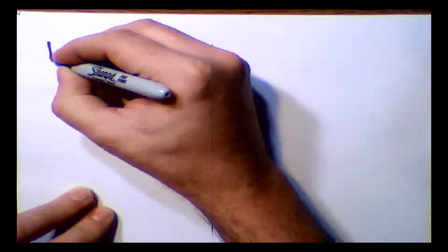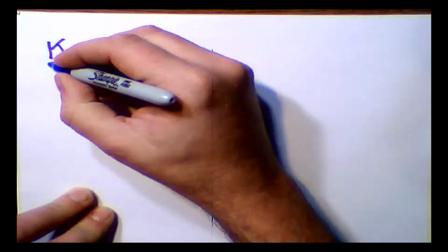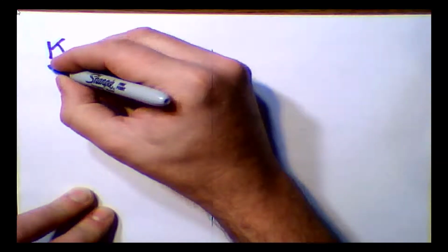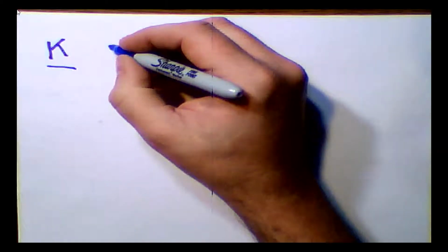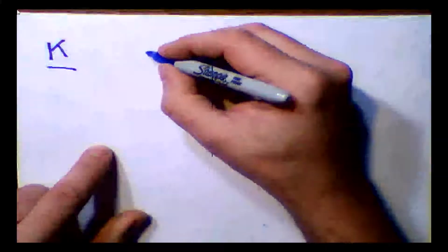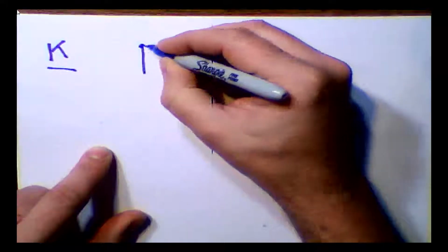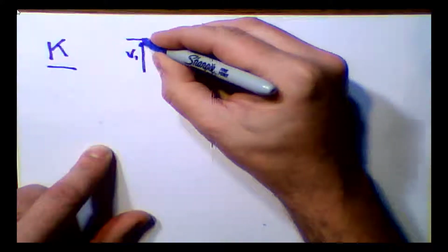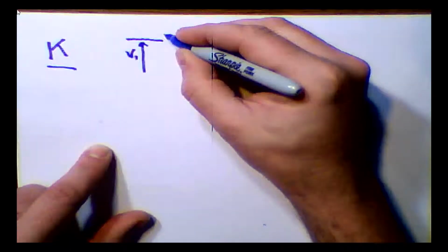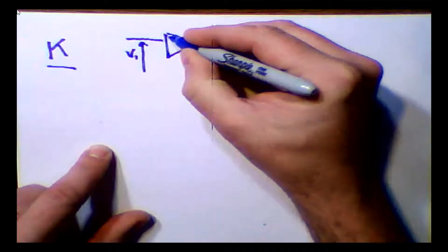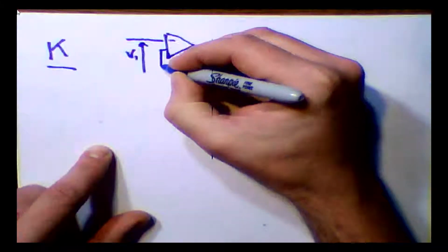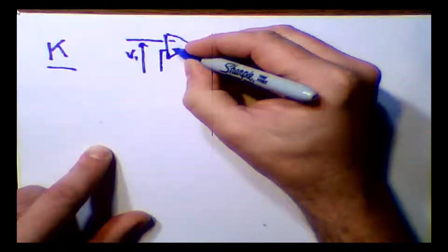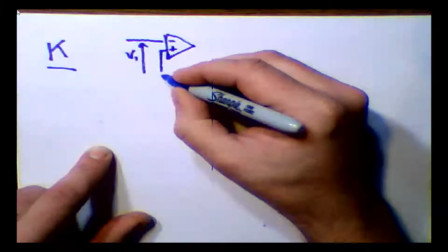So let us begin with again K. That we have done already. It is sufficient to do the following. We have V1 here. We feed into the negative pole of the op amp. We link the positive pole of the op amp to the ground.